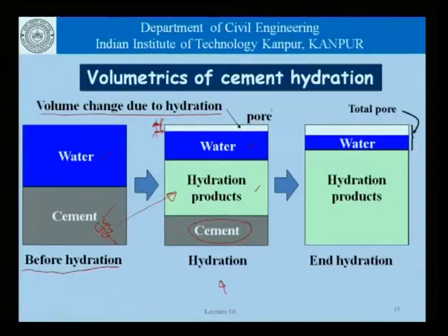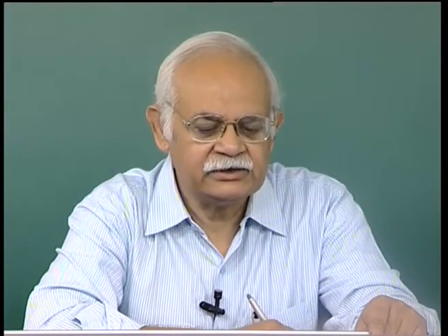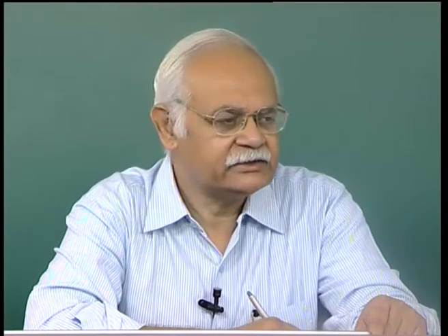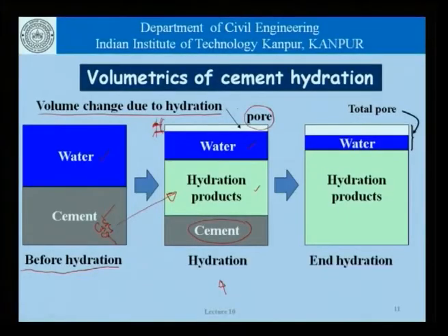So, these are the pores which have got generated as a result of changes in volume, the hydration products occupying just a shade smaller volume compared to the reactants.